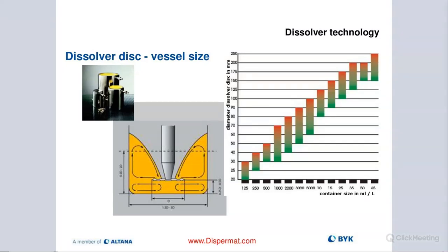So when we start out, we're going to have to fill our container depending on the volume that we want to do. Basically, we want to look at 2 things. We want to first look at the fill rate. We want to stay at about a 50% fill rate in our container. We don't want to go much over it. We have maybe a maximum of about 70%, but that's really the absolute maximum.